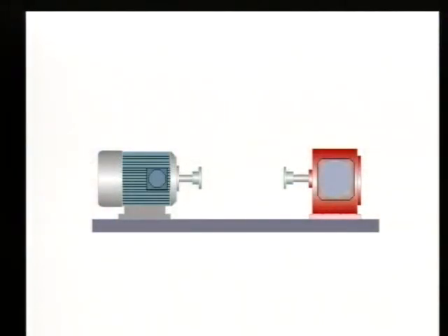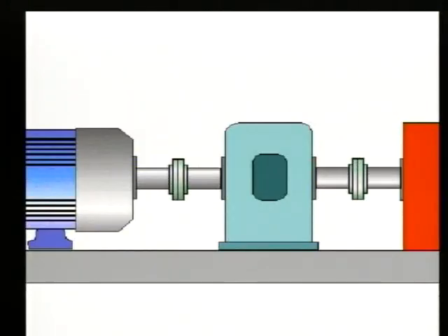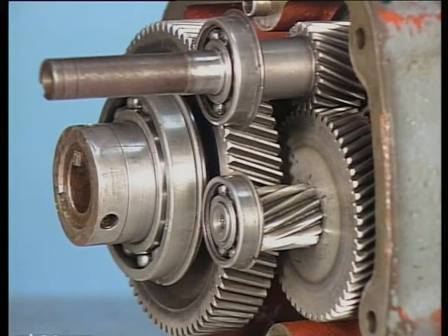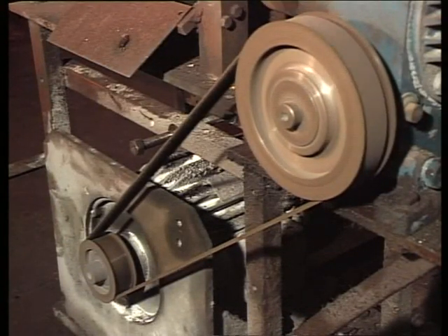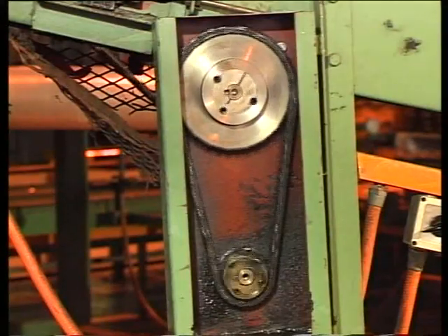Between the motor and the machine, there is most usually a reduction device, which converts the AC motor's shaft speed to the desired speed required by the input shaft of the driven machine. The term reduction simply means a slowing down in revolutions per minute between a driver and a driven shaft. The term geared reduction means that the process of reduction is made via the use of gears of one kind or another. Other methods of reduction include drive belts and roller chains.